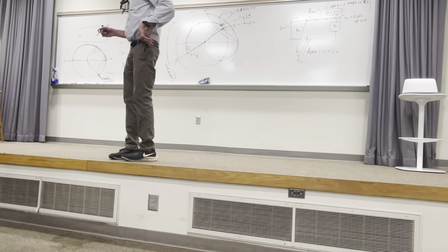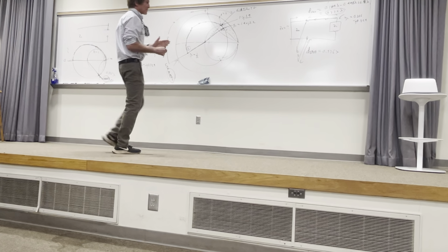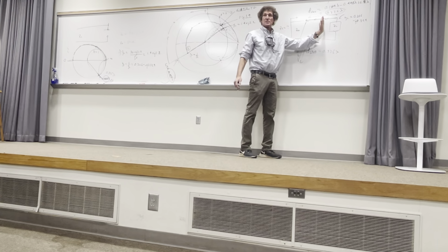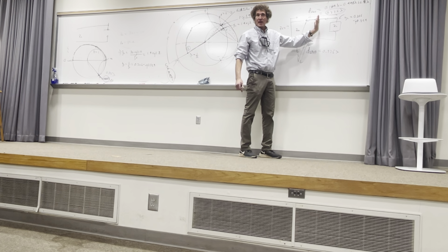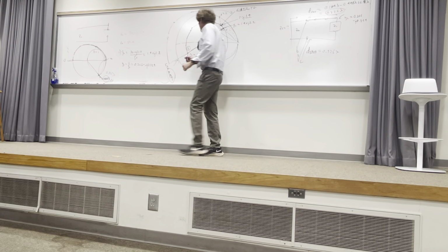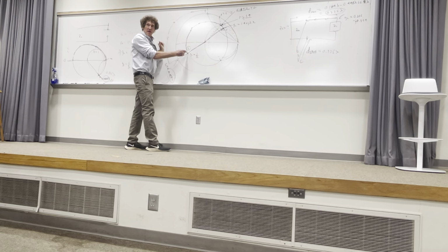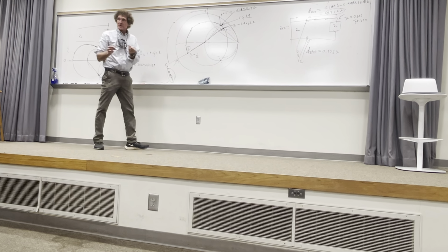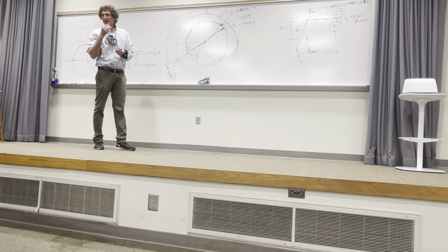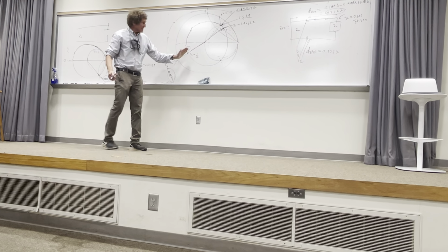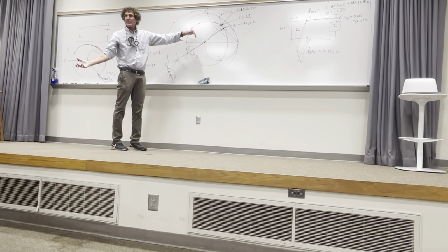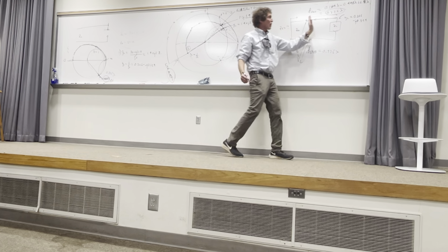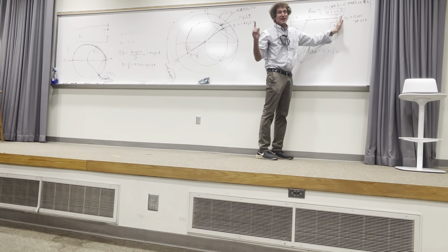Well, remember, as we move away from here, we're moving on a circle of constant reflection coefficient magnitude. The real part and the imaginary part are changing simultaneously. So when I'm moving on this arc, in the admittance domain, the values are changing continually, but the radial distance is constant. So don't worry about it. The values are going to change, but that reflection coefficient is going to have the same magnitude always. So standing wave ratio on this section will always be the same, and it will not be 1. Got me on that, class?